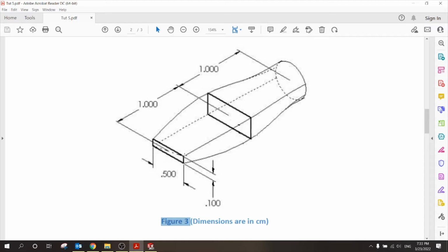That means extrude, but starts with a small rectangle and ends with a big rectangle. When I finish, I can create a new plane with a circle and make a new loft. Or I can start with a small rectangle, big rectangle, and a circle, and in one shot I can do the 3 planes in one loft command. Okay? So the distance between the planes is 1 and 1.